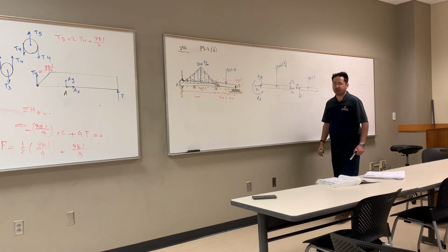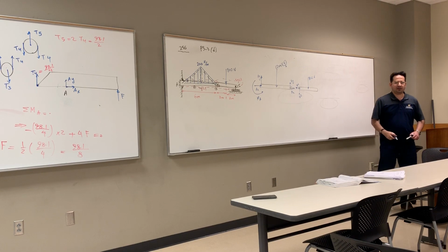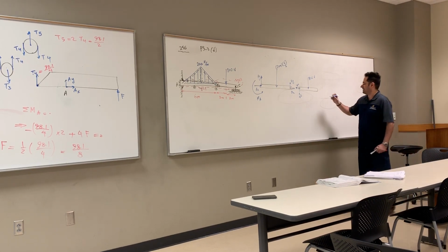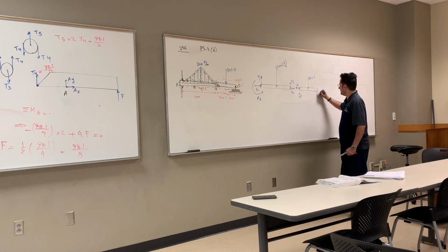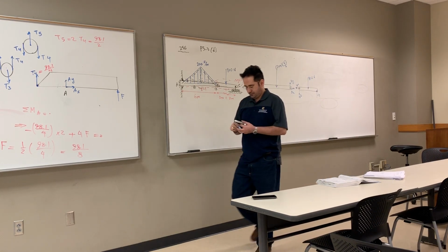From here, what about point C? Yeah. How many force and moment at C? Just one in Y, right? You can easily move it in X. So one Cy. And that's it. That's my FBD.